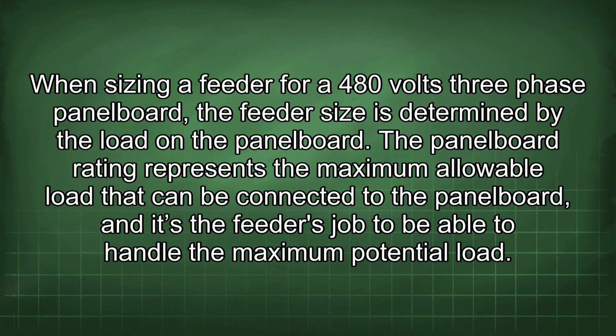When sizing a feeder for a 480 volts 3-phase panel board, the feeder size is determined by the load on the panel board. The panel board rating represents the maximum allowable load that can be connected to the panel board, and it's the feeder's job to be able to handle the maximum potential load.